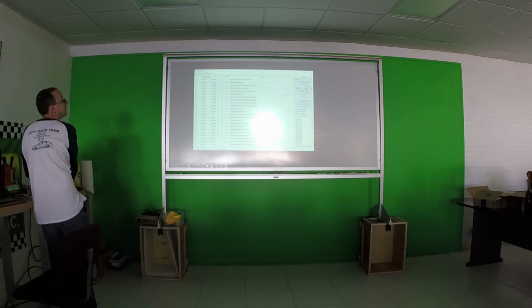As I covered before, when you see in the frames, you get a timestamp, ID, whether it's extended or standard frames. Extended would be the ones that have 29-bit addresses. Standard just have 11-bit. Then which bus it's on, the length, and the data bytes. Now, in this program, anytime you see a hex value, it really will be preceded by 0x. So that tells you that this is all hexadecimal.